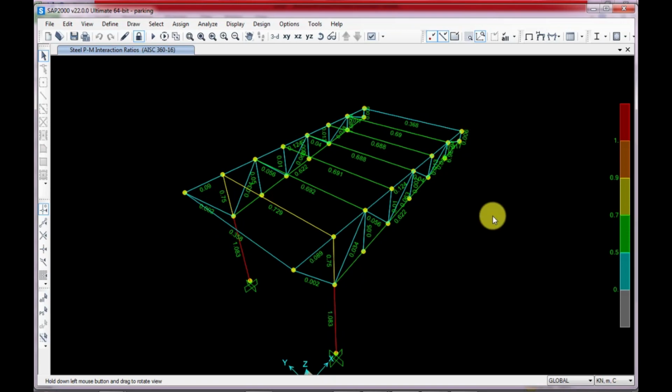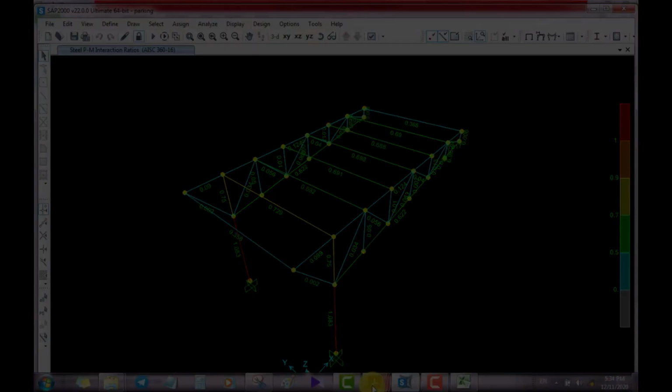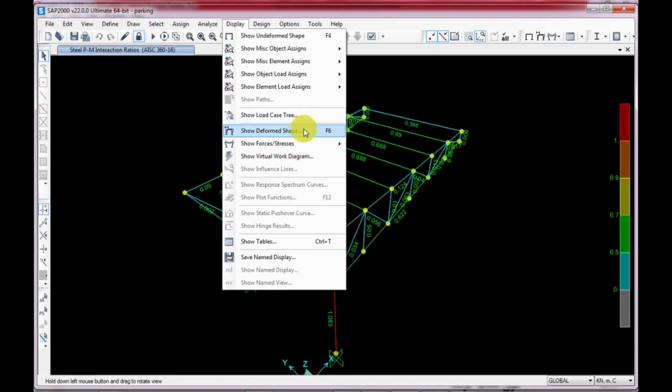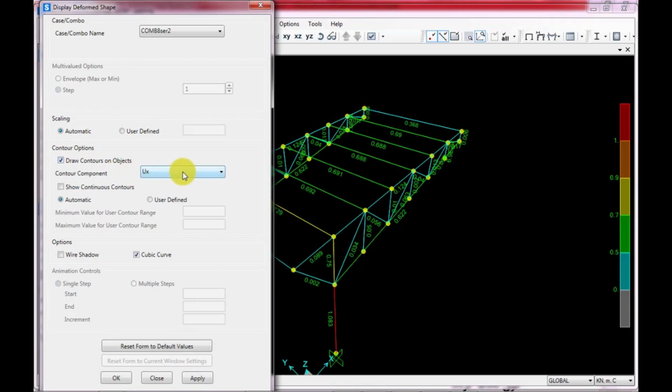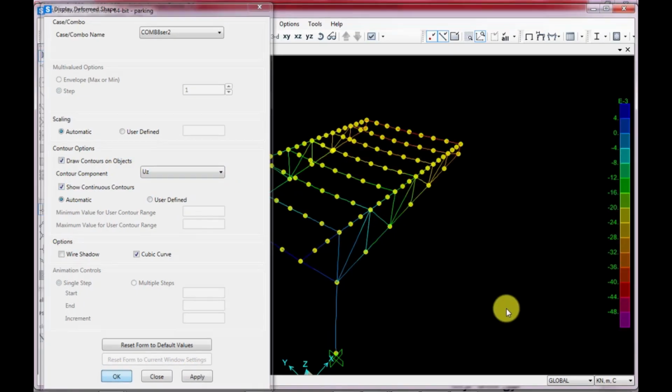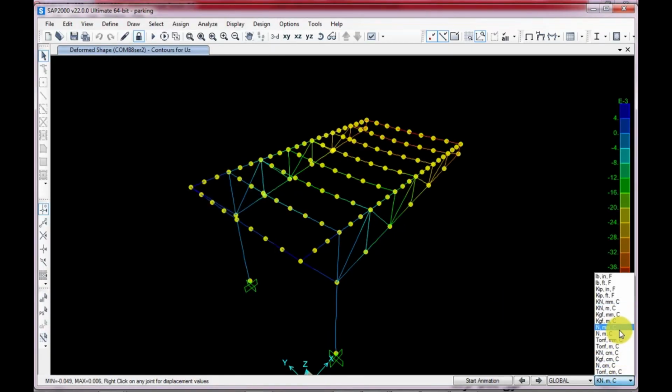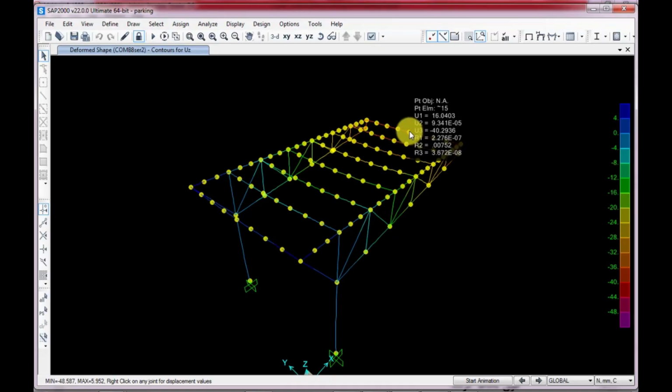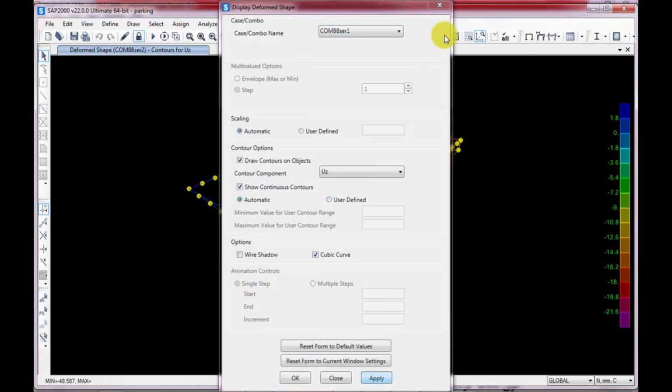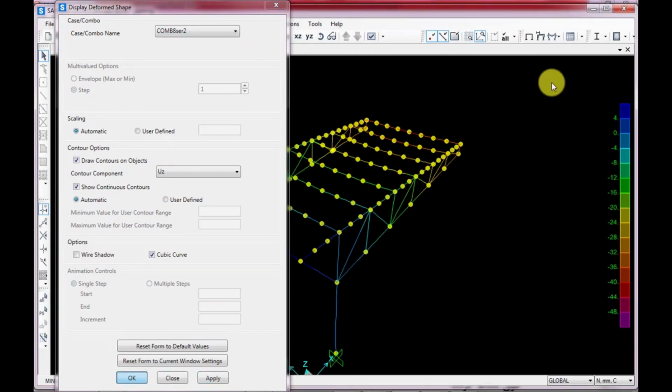So we distinguish between total structural movement and relative truss deformation. The critical value is the relative deformation, which is about 5 millimeters. The structure is completely acceptable in serviceability. Also, all members satisfy strength requirements, so the final design is safe and approved.